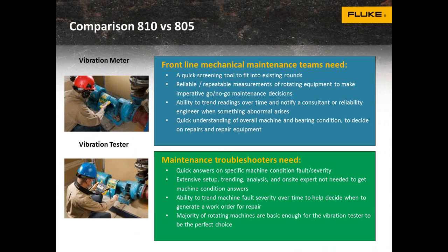Do you have to set up the bearing database? That's a good question. No, because the diagnostic engine inside the 810 uses pattern recognition, and by using this pattern recognition, we can follow the bearing wear that occurs in all roller type bearings. We use something called the 9 stages of bearing wear. As the bearing progresses from slight to moderate to serious to extreme, those patterns have all been saved, and those rules are all within the 810.